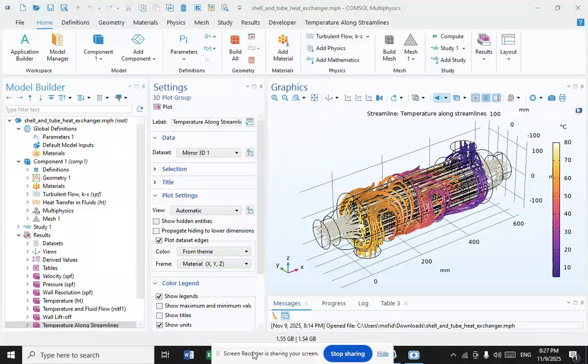There are different types of plates available, including plate and frame, plate and shell, and spiral plate heat exchangers. The distribution area guarantees the flow of fluid to the whole heat transfer surface. This helps to prevent a stagnant area that can cause accumulation of unwanted material on solid surfaces. High flow turbulence between plates results in a greater transfer of heat and a decrease in pressure.